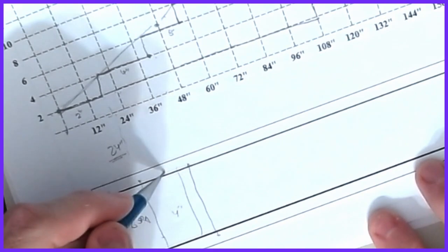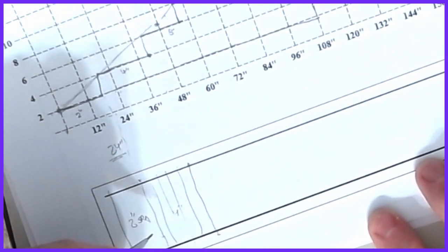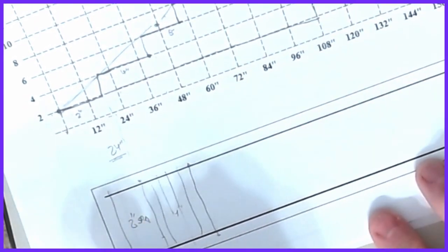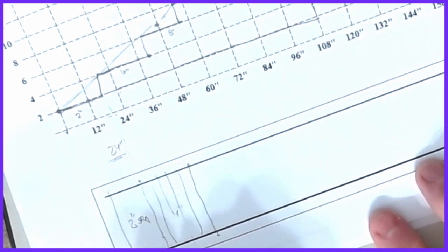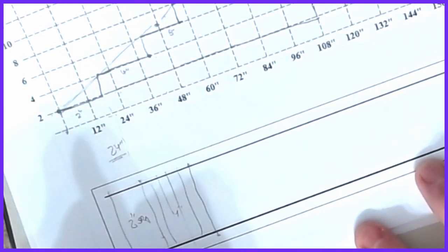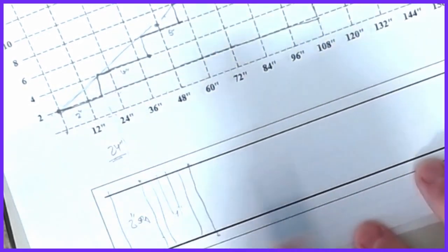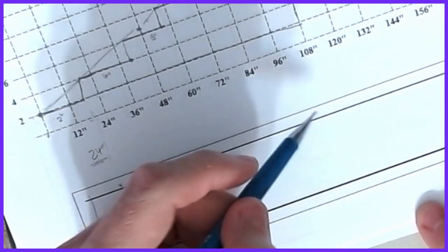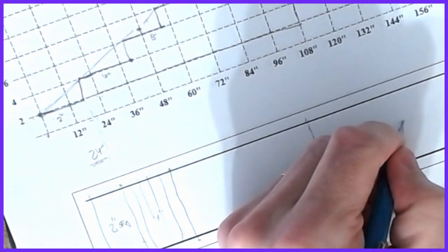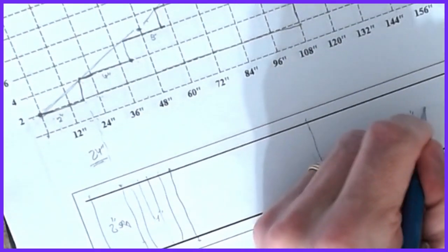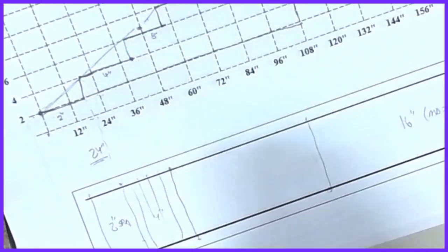And then, when you do your detail drawing, you can actually draw these in at true scale or whatever. But that's the way that you can lay this thing out. And eventually, as a running dimension, I do 9 stirrups at 2 inches, and then I do 6 at 4, and I can build this diagram all the way out. And then eventually I get out here in the middle somewhere. Okay, and now my S max is starting to control. That's my 16 inches max, and then you can quantify this.